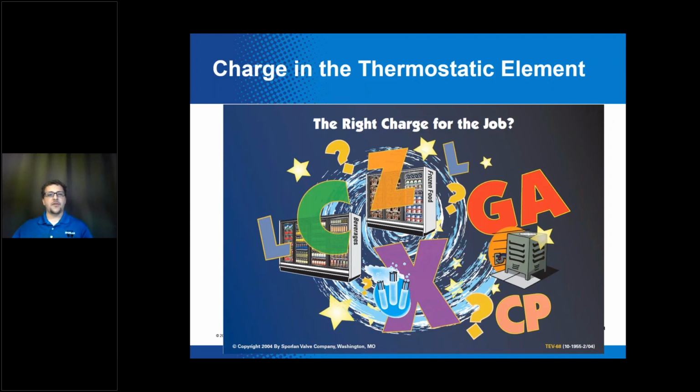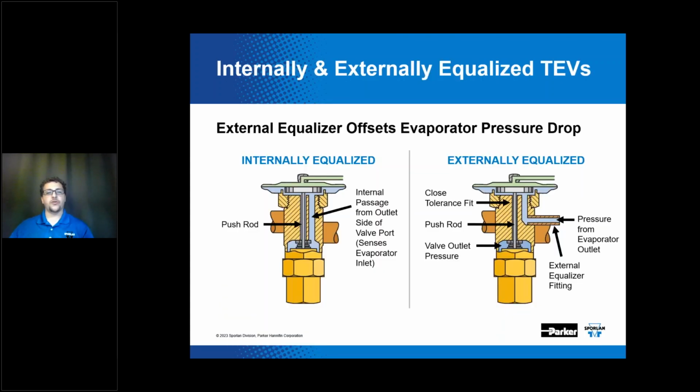So we'll tie this together under the troubleshooting, but having an improper thermostatic charge for the application is definitely going to result in inconsistent or unsatisfactory superheat control, even if you have that valve sized properly. So even if the valve is properly sized for the capacity, it is still not going to effectively control superheat if you've got that wrong charge relative to the application you're trying to use it on. And again, we'll go into that more under the troubleshooting piece.